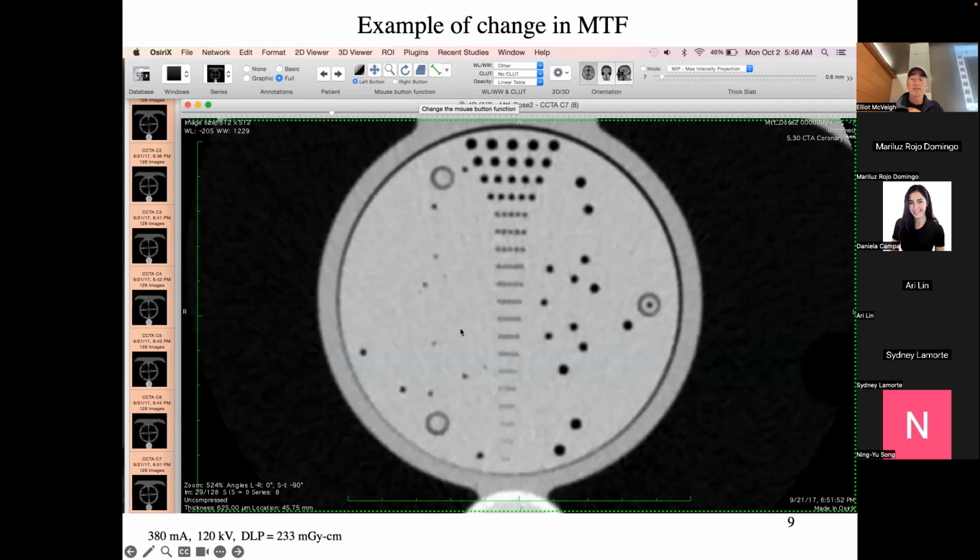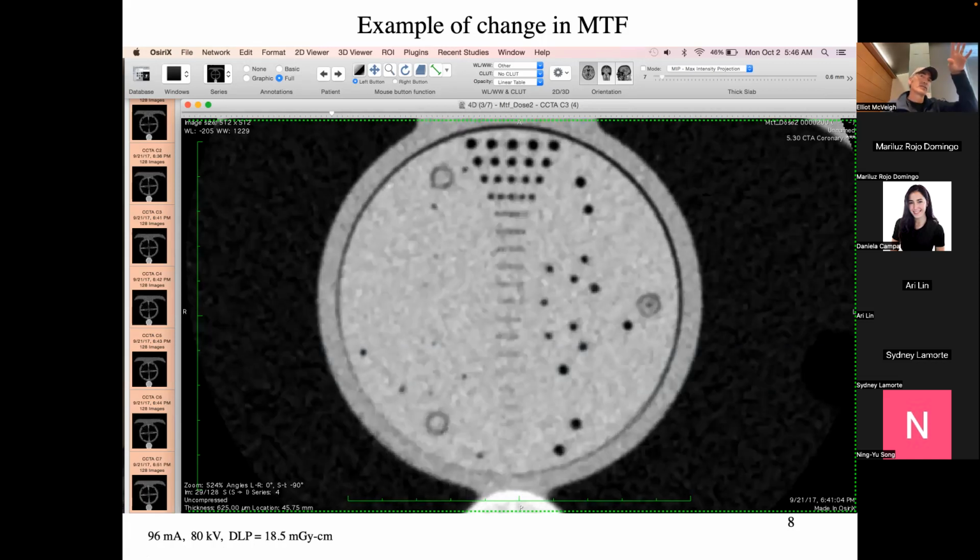right? But also, and this is something about CT scanning, the manufacturer, when they get down to a low number of photons, will start averaging things together in the raw data. And when that happens, they start losing spatial resolution, right? In order to keep the signal to noise of the background reasonable, they'll start averaging stuff together. And so it affects the modulation transfer function.